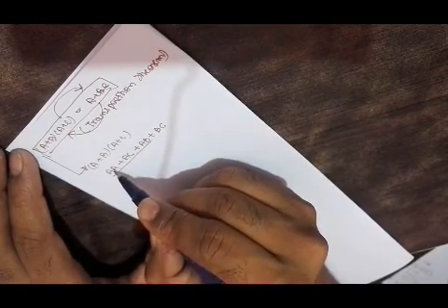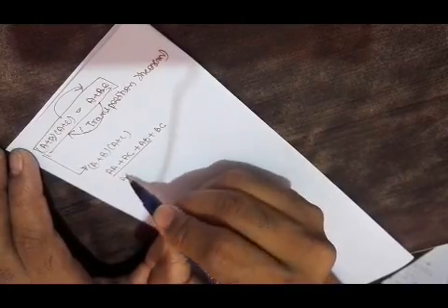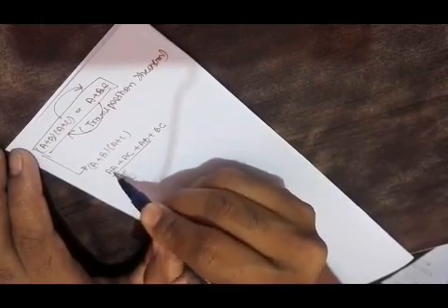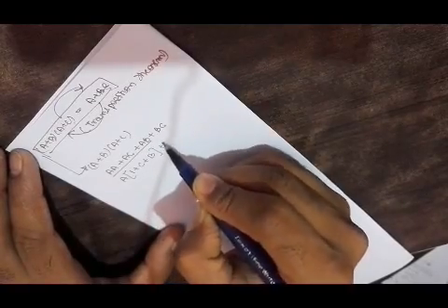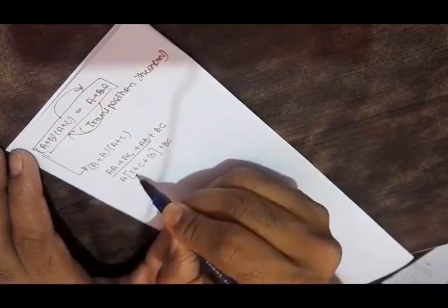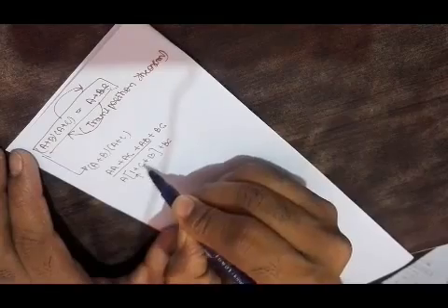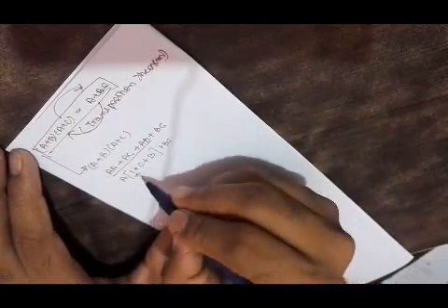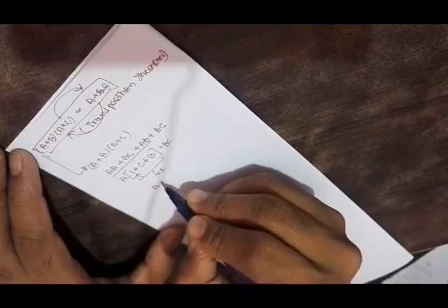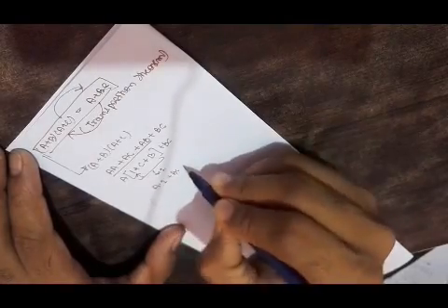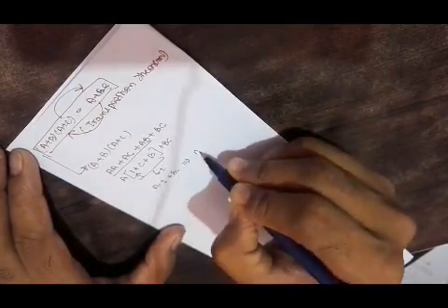A itself, right? We're using the AND property. A·A is A. So this is A. If I take A common, this will remain 1, plus C plus B plus BC. I said if any one of the inputs is 1, and these are all OR operations, plus and plus, so this whole bracket will give us 1. So A·1 plus BC, and this is nothing but A + BC.